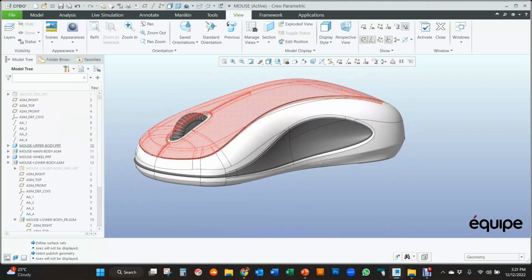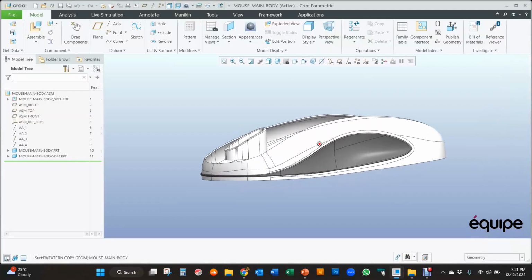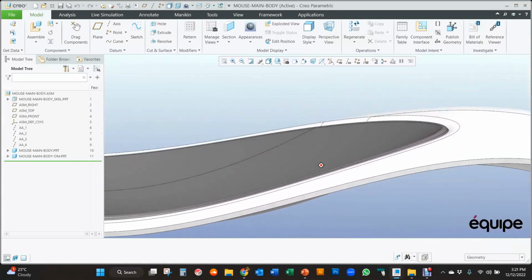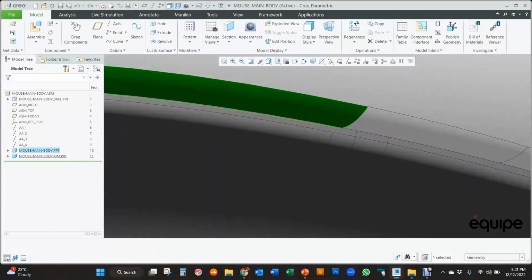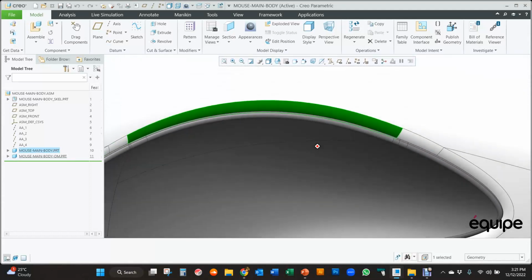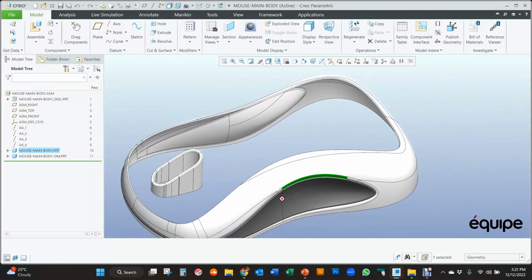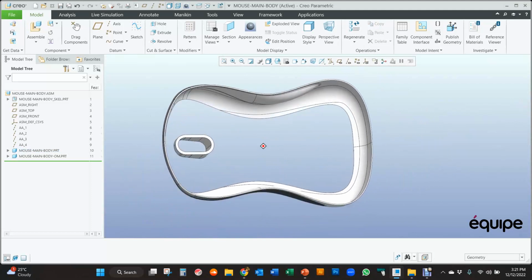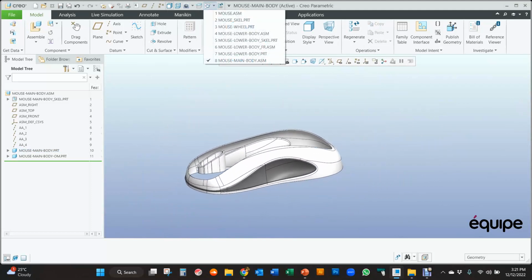It's fantastic for these sorts of areas where you've got overmolded parts, you've got a substrate part, and you want to ensure that your overmolding tool is going to blank off nicely around these surfaces here. You want nice, good, clean part lines. And so again, we're using those common surfaces just to ensure that we're getting the best quality product at the end of the production line as we can.